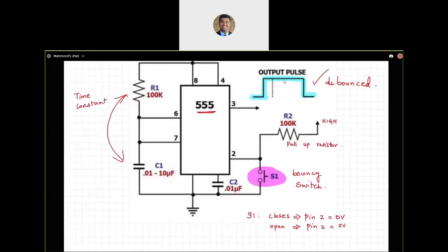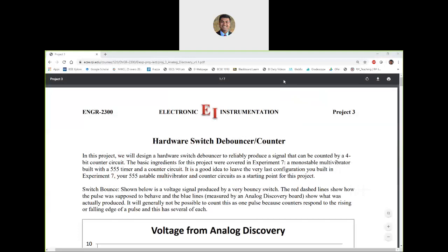And the goal is to choose a big enough capacitor and a big enough R1 such that the capacitor does not discharge instantly. So by holding that charge for a controlled amount of time, typically it is going to be related to the bounce times, average bounce times for certain switches, maybe 30, 40 milliseconds, maybe 60 milliseconds.